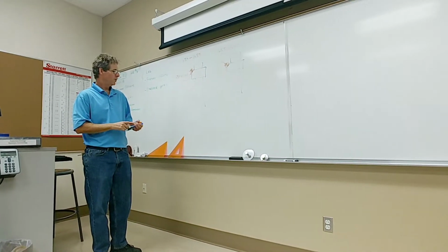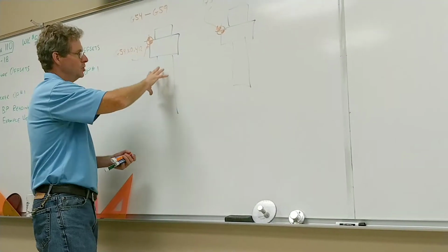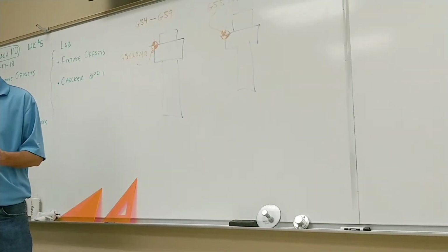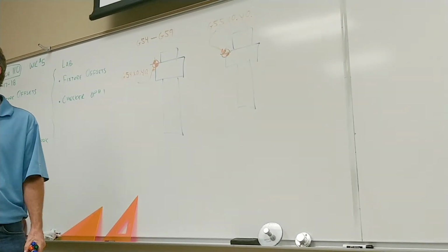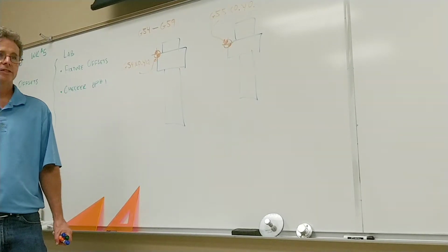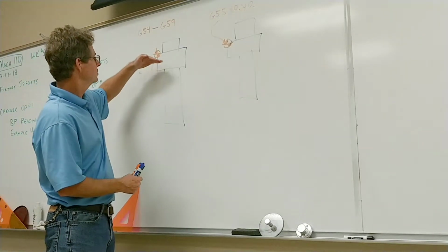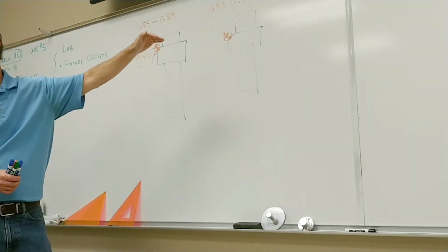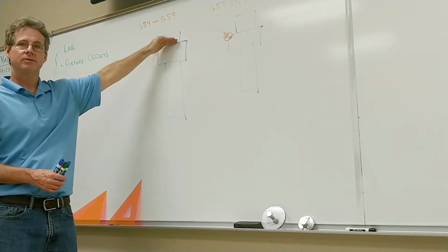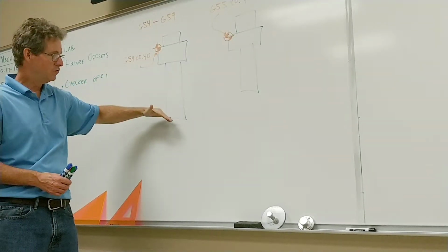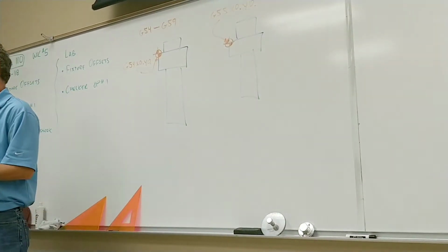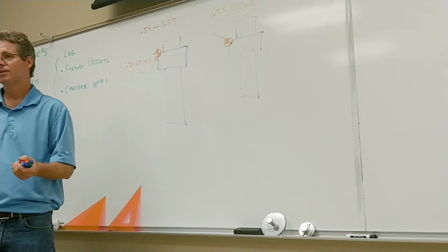So with the devices that we have on the table, the movable jaw is on the bottom of the part, right? So when I do decide to set fixture offsets, I have to consider a couple of things. First of all, I always want to set a fixture offset on a hard position that's never going to move. Okay? So when I set a fixture offset, in the example of a standard single station Kurt style vise, I'm always going to put it against the hard jaw on the back edge. I'm never going to put it on the front, because this vise can change. Okay? And if I set it to the front, you would think, okay, so I buy a piece of 2-inch material, what's going to change?